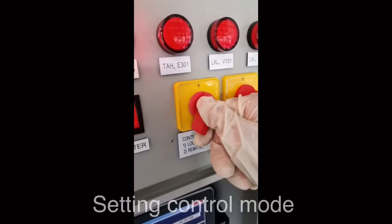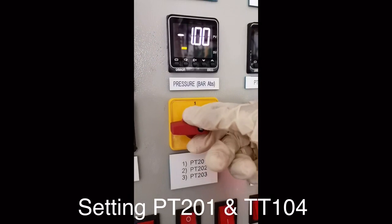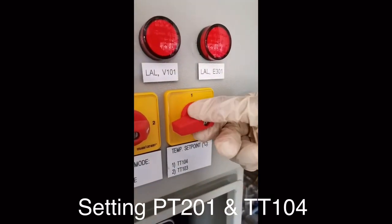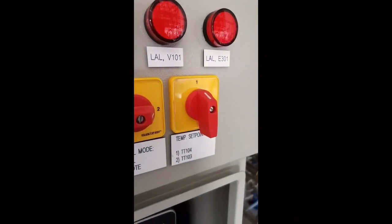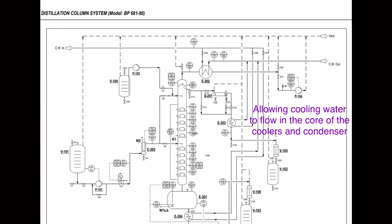Then at the control panel, set to the remote position 2, PT201 at position 1 and TT104 at position 1. Next step, partially open valves V25, V26 as well as V27.